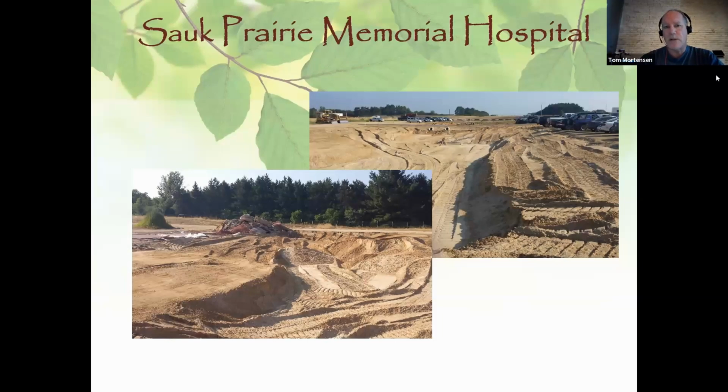And then there's also parts just here, even around Metro Milwaukee, that are just hard pan blue clay. So you can't apply the same infiltration or technical standard to green infrastructure in those two types of soils. One is going to work well, one is probably not going to work at all. So how do you develop a strategy around that?